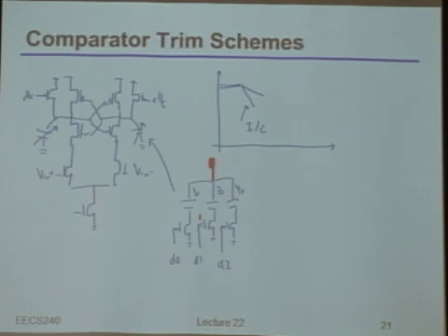So let's go back to our earlier example. Let's say that you wanted 1 millivolt of residual offset resolution, and you also had a 100 millivolt 3 sigma range you needed to cover. What might be painful about doing the offset cancellation this way? Okay, you said it's a lot of caps. Why is that bad? Okay, you said they'll never be completely off, right?